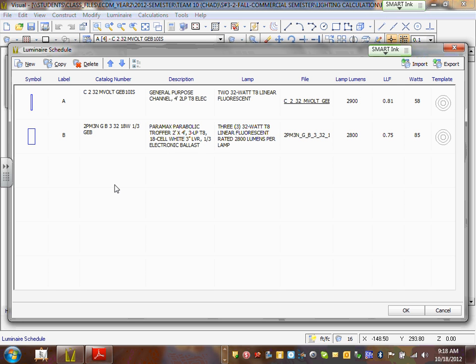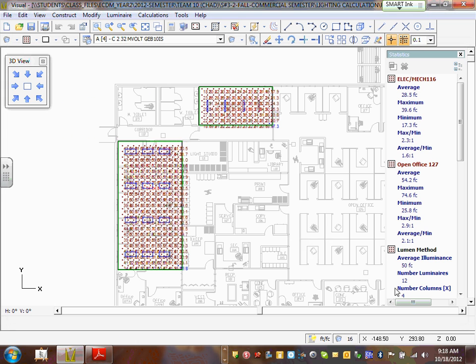Here's the drawback, the disadvantage. Call it B, because the system doesn't name it. So that's going to become fixture B. Okay, and exit. So that's fixture B. You can change any number or name that you want. The drawback: every time you bring the fixture this way, it will bring it into the schedule as another brand new fixture. So when you bring the same fixture one more time, just delete it because it has been used.